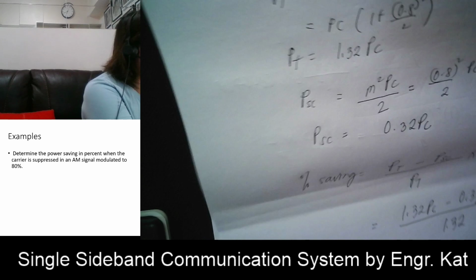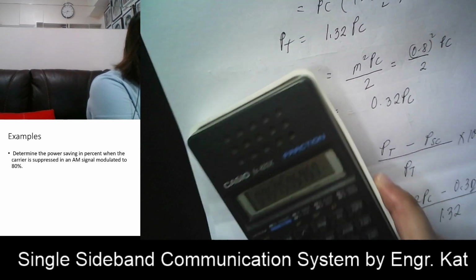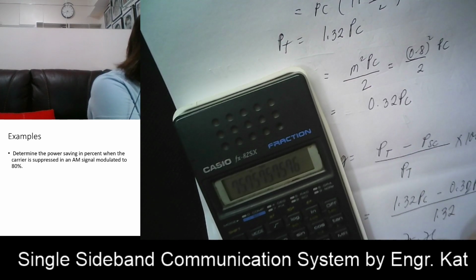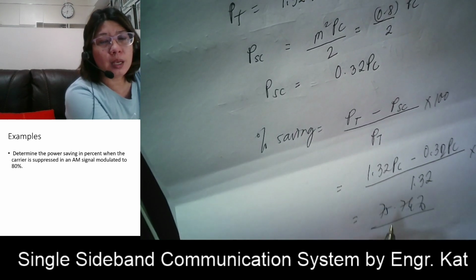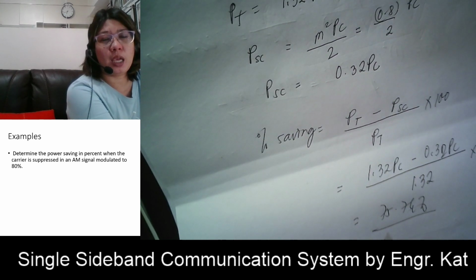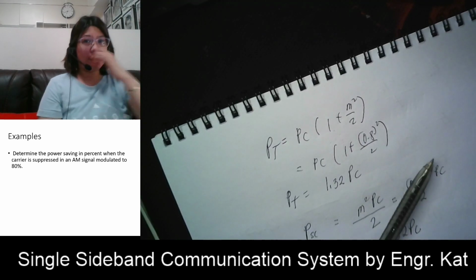Okay? So we have there 1.32 minus 0.32 divided by 1.32, times 100. So that will give you 75.76%. So this is the total power that was saved when we transmit your AM using a double sideband suppressed carrier compared with the conventional AM having a full carrier. So you have a power saving of 75.76%. Okay, so that is how you do that.